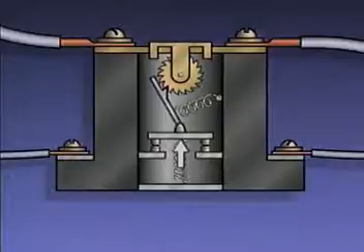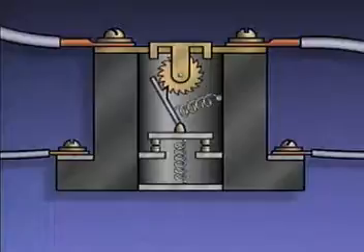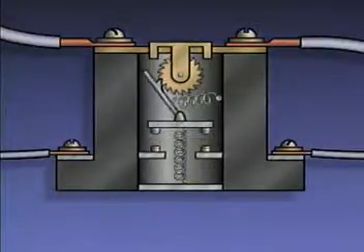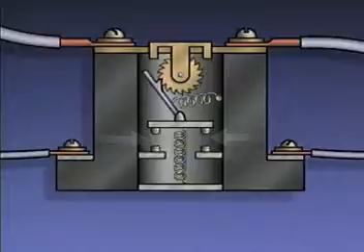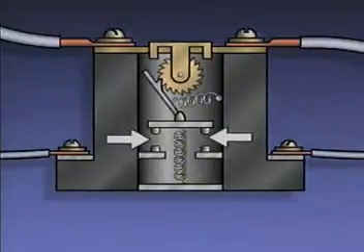The contact spring is positioned so that its force works on the mechanical linkage to attempt to turn the ratchet wheel. When the current level causes the heater to generate enough heat to melt the solder, the liquid solder cannot hold the rod, so the force of the contact spring causes the ratchet wheel to rotate. As the wheel turns, the linkage moves, opening the contacts of the overload device and interrupting the current flow in the control circuit to the M-coil.